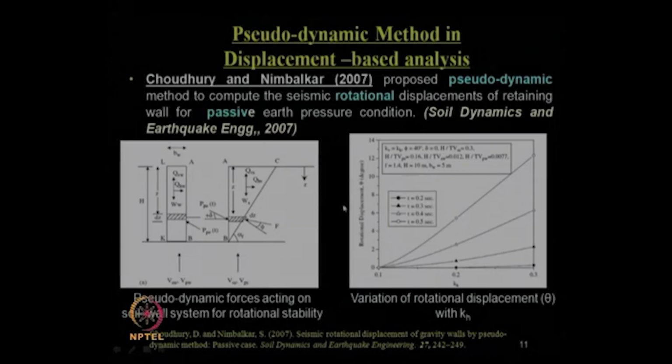If that value of rotational displacement is more than the acceptable or permissible limit given by the designers or the owner of the property, or as a designer you decide that you will not allow displacement more than this, that is performance based design, if you want to carry it out, in that case you can restrict the displacement in that manner and redesign the section, so that rotational stability is also ensured under that magnitude of earthquake input motion. Clear?